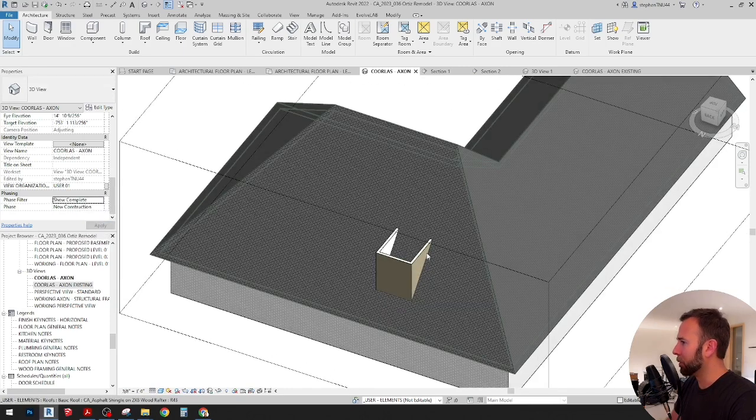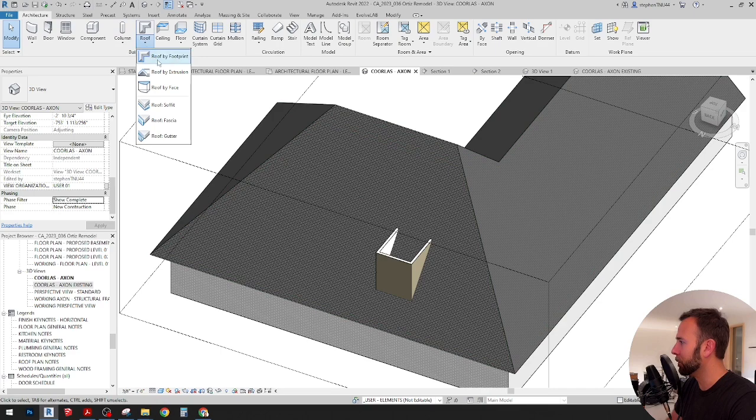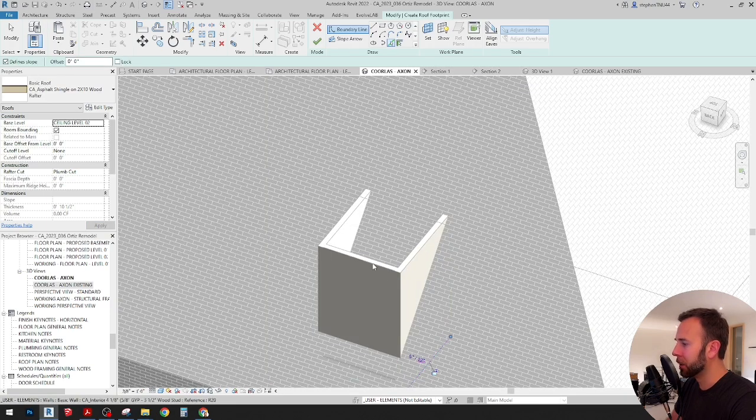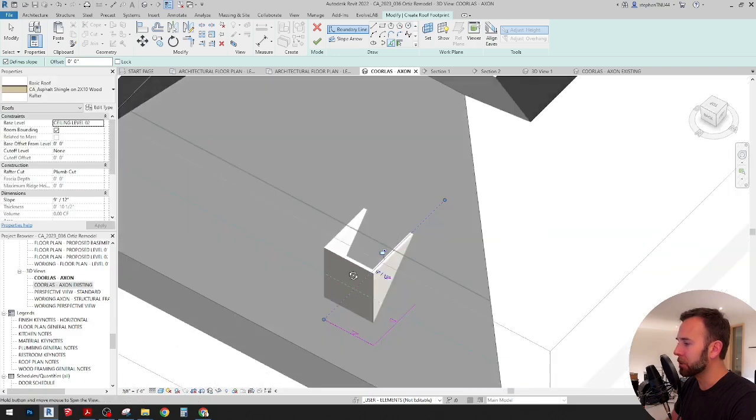So I'm going to drop a quick roof on there, show you guys how to throw a dormer in so we can get the ceiling plane in and see what our complete space looks like. So if I go back to roof by footprint, and see if I have the option to, yes, put this on ceiling level 2. Sometimes it doesn't hold to that even after you model it in place there, but let's just give it a try. And I'm going to grab those lines,